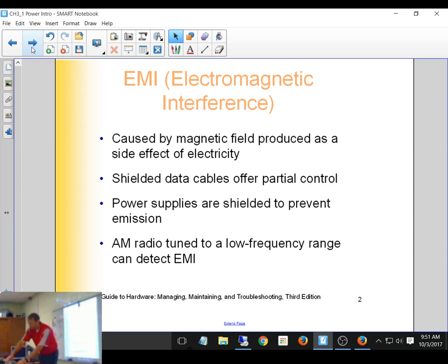Okay, so that's one thing that I didn't even realize would cause such a problem with weird things like our cabling, and it can cause the same thing with our network cables. If we've got a network cable bundle running, those cables aren't really putting out enough electrical current to interfere with each other. But if all of a sudden the new electricians run a big, huge wire right over top of them and lay it right on top of it, all of a sudden we have wires that don't work.